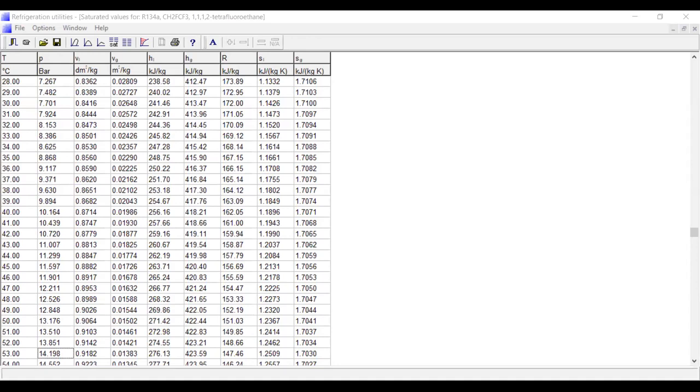Okay, so at 7 bar this liquid, and also there can be vapor here, but here by right it should be liquid only. And then when we suck this liquid through this tiny hole, this flashes, that's the word, meaning it partially turns into vapor, and this becomes two-phase. Okay, and then pressure is reduced.